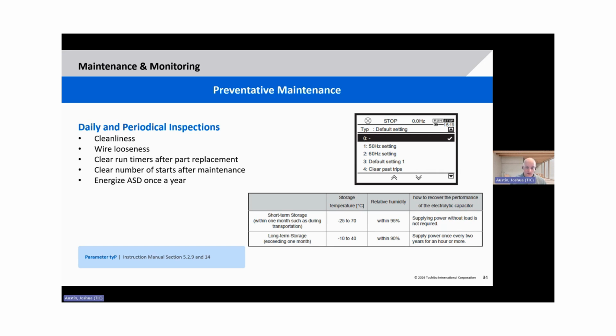And then the last one, this is probably the most important one on the list, is that if you have a drive that's in storage or it has been without power applied for close to a year or longer than a year, then you need to energize that drive so that the capacitors do not lose their form or performance.